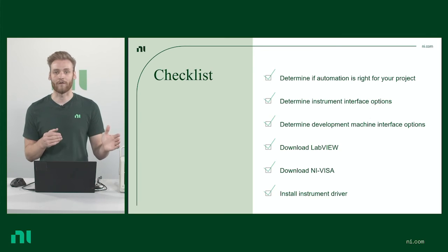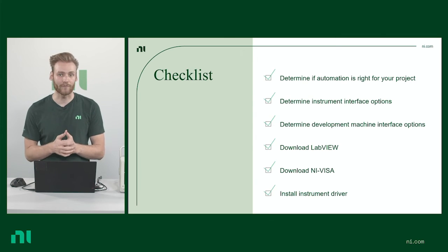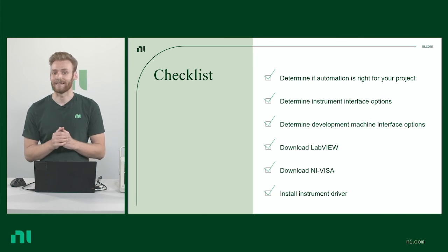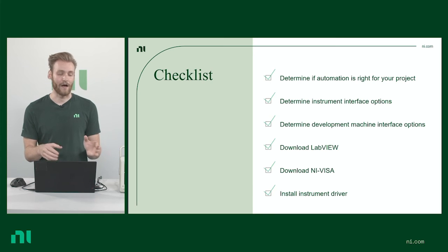So once you get that all figured out and you're able to communicate, then that's when you start thinking about software. I obviously highly recommend using LabVIEW. You can download LabVIEW for a free trial, and I guarantee you within that trial you'll be able to get this all figured out. Once you have LabVIEW, you can download NI-VISA, which again is going to be that driver that handles all the low-level communication between the different interfaces. And then finally, you'll want to install the particular instrument driver.